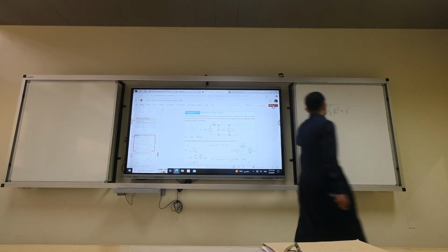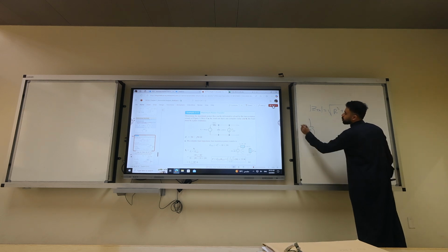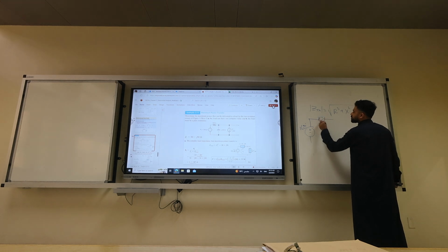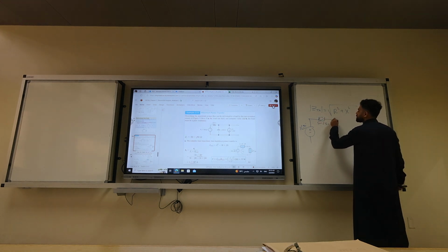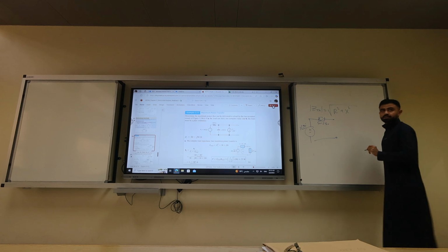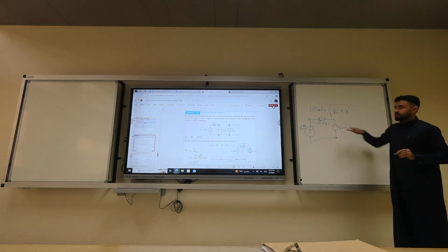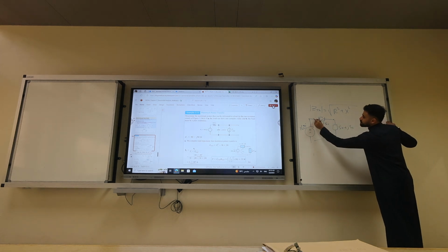So what we had is V Thévenin, 100 angle minus 90, and we had what? A load of 50 minus j50. So what's the maximum power occurs at? It occurs with a load of 50 plus j50. Get it? So what's the current?